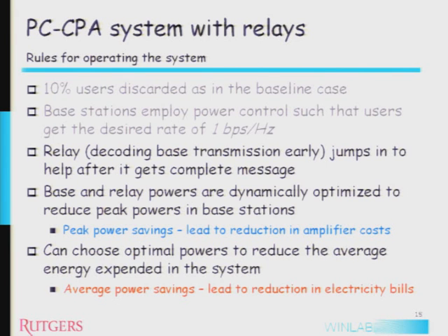So how exactly is it done? When the relay transmits, the base station transmits simultaneously with the relay, but with a different code. The same information, but a different code. So it's kind of a two-step process, but these are going to happen at different times. Each relay in the system is going to get information at different times, so you don't have to have a slotted system.